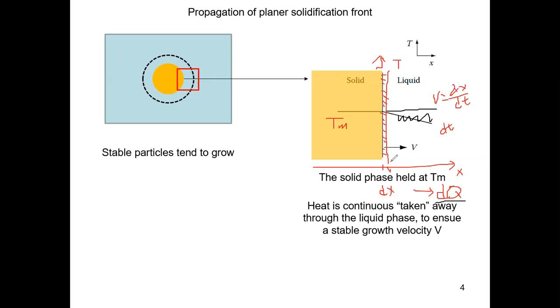No, right? Because the heat is still here. So this small amount of solid will not be stable. If you're not taking the heat away, this thing is going to absorb this extra heat in the system, locally here, and then melt back into the liquid. So in this case, if you do not induce any temperature gradient in the liquid, the solid will not grow. It just remains stable like that, but it's a kind of dynamic stability. On average, it won't grow. It will constantly form and melt, constantly solidify and melt.